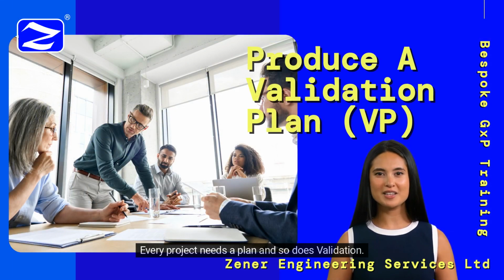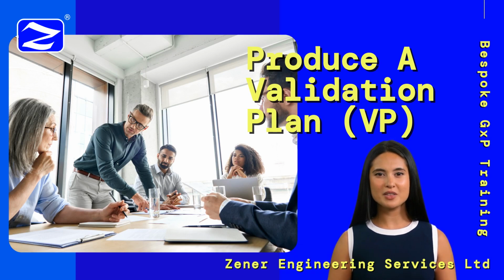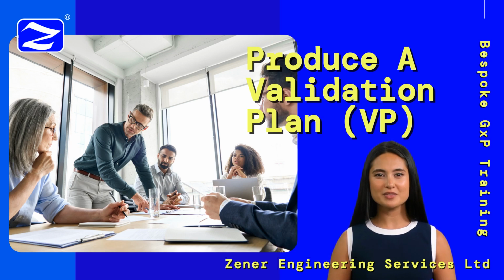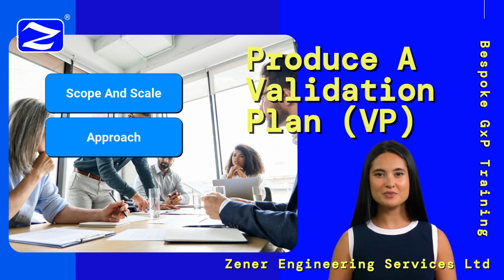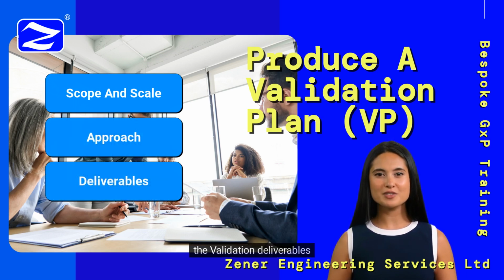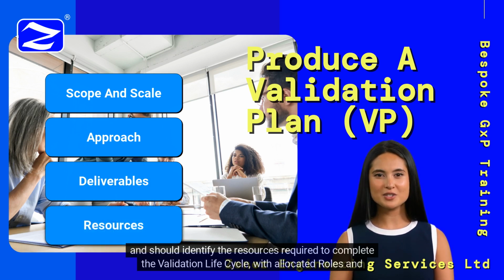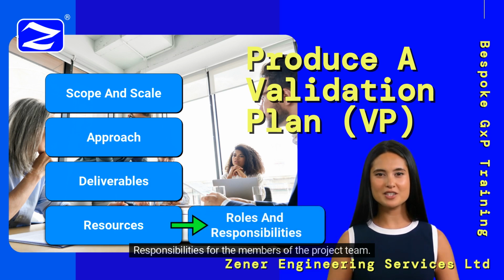Every project needs a plan, and so does validation. Whilst the URS is being drafted, I strongly recommend that a validation plan is also drafted in tandem. The validation plan should document a number of considerations, including the scope and scale of the validation exercise, the anticipated validation risk-based approach, the validation deliverables, and should identify the resources required to complete the validation life cycle with allocated roles and responsibilities for the members of the project team.